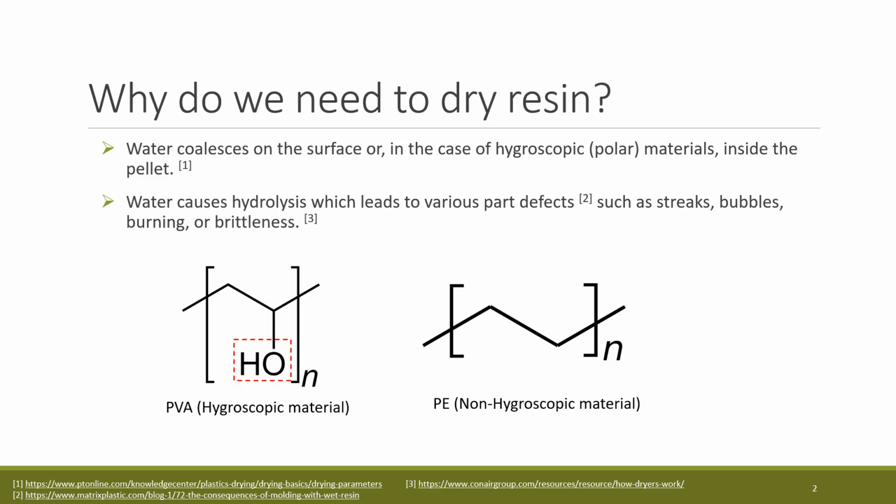Processing resins with moisture present causes hydrolysis, the chemical breakdown of a compound due to a reaction with water. This is akin to thermal degradation. This causes various part defects such as streaks, bubbles, burning, or brittleness.